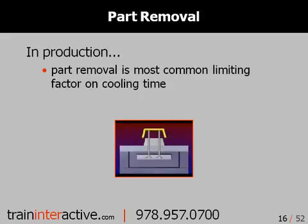Now we're going to discuss part removal or part ejection. With injection molding, cooling time is dependent on being able to evenly cool a plastic part and prepare it for ejection. In this example, we have pin ejection. I chose this example to illustrate a point. You'll note that with pin ejection, it quickly becomes complicated to route water lines. Basically, the more pins you add, the more difficult it becomes to add cooling lines.